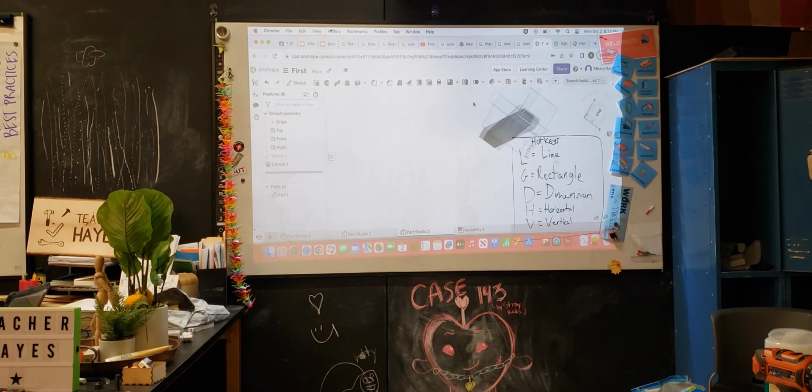Also dimension semi-quickly, as I created a beam. It's supposed to be a metal tube. You don't need to do this, but I want to go over another cool thing about Onshape. I have this 3D part, a beam. One thing you can do on Onshape is click on a face, double click, and create a new sketch.